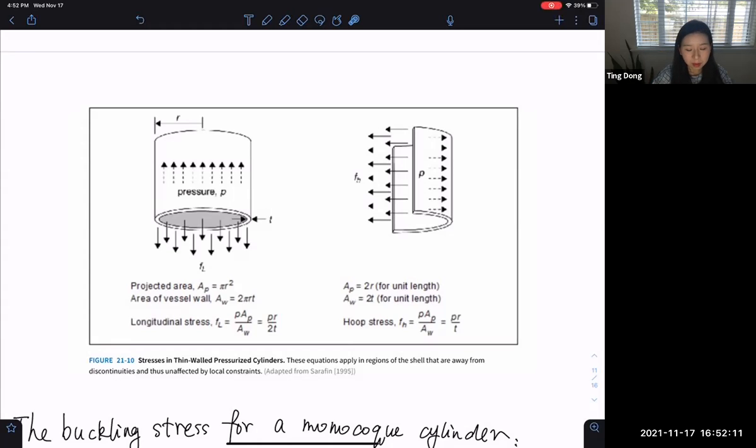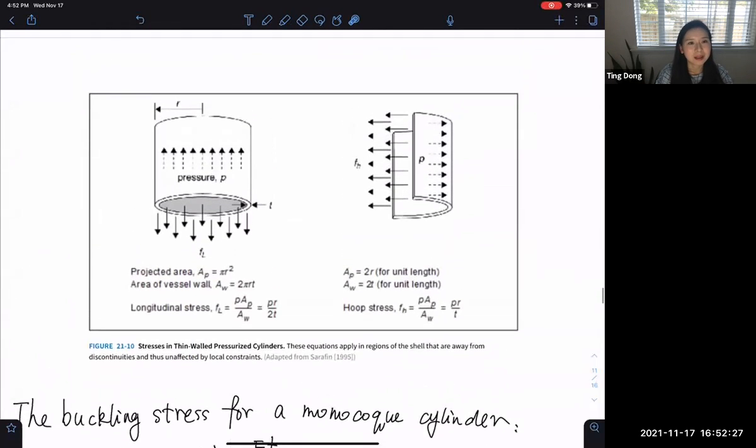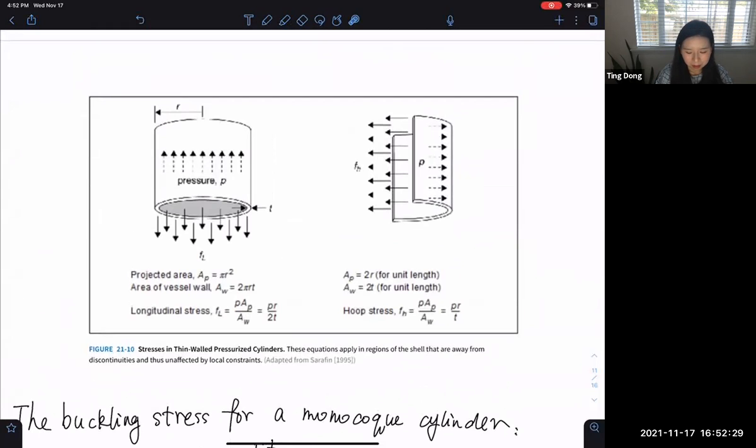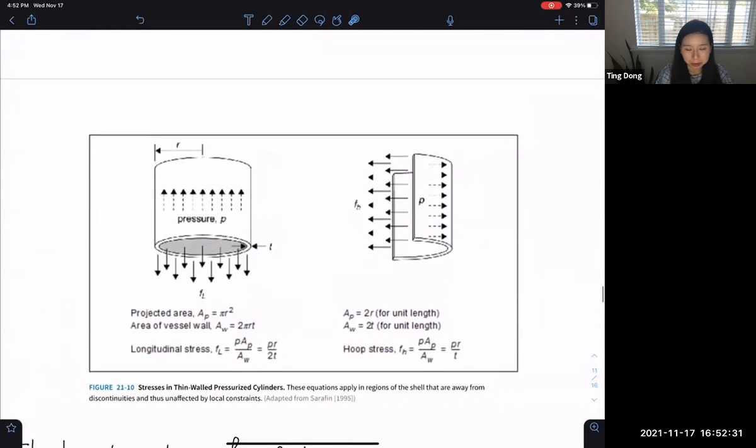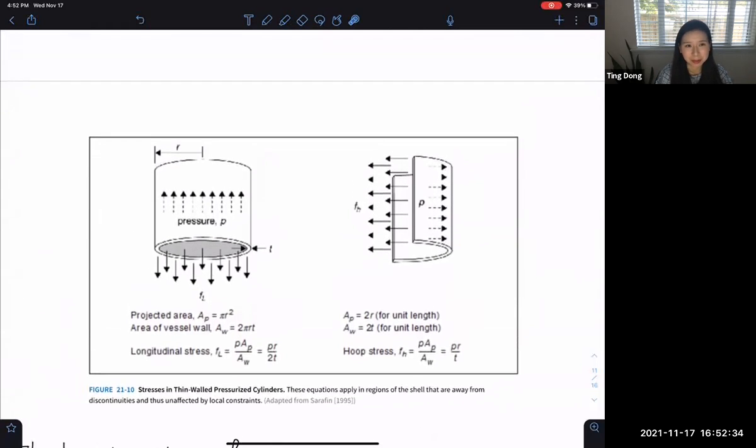If it's several orders of magnitude off from the actual stress from hand calculation, it means that your software result is wrong. So this is something we want to make sure of in your structure analysis: don't just show a beautiful picture when the result doesn't make any sense.